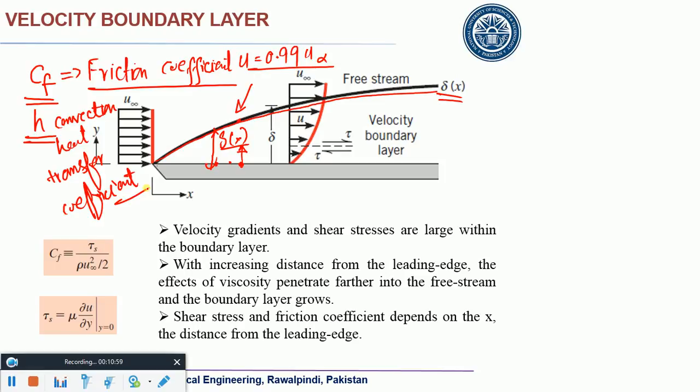Right now, just see, you see there is friction. If you look at this velocity layer, the fluid layer which is sticking to that solid would have zero velocity. There is friction, and as you move up, that velocity increases. It means due to that friction, there is something known as shear stress. I hope you remember that. You remember that tau term?